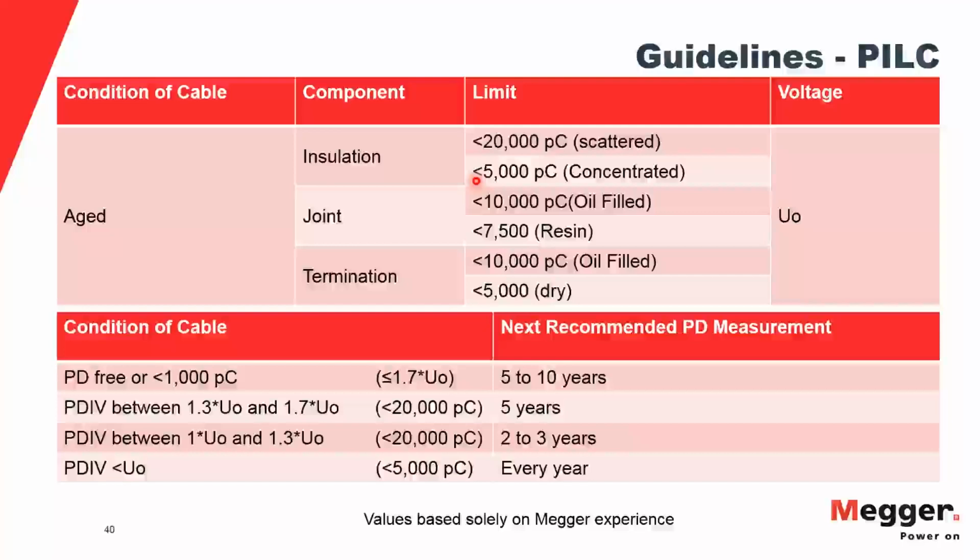That's a very good question, and ultimately that is the whole point of this webinar, to illustrate the point that if you're only using VLF Sine technology for partial discharge testing, you may miss partial discharges, and you would never know. There's no way for you to know that if you're only using VLF Sine. So how do you cope with it? You cope with it by using a different technology. You use damped AC or cosine rectangular. You use something that's closer to power frequency.